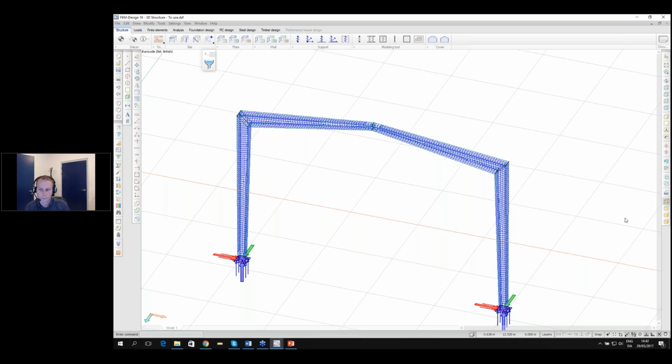Also with the shells, you get all your forces in your welds. You don't do that with the bars unless you have one of those solutions we have implemented in our steel joint design. You can also make holes in your plates for pipes. Right now they're just massive, but you can make all the holes you want, and you will still get an exact result which you cannot do in a bar model. So it's for two different kinds of analysis problems.